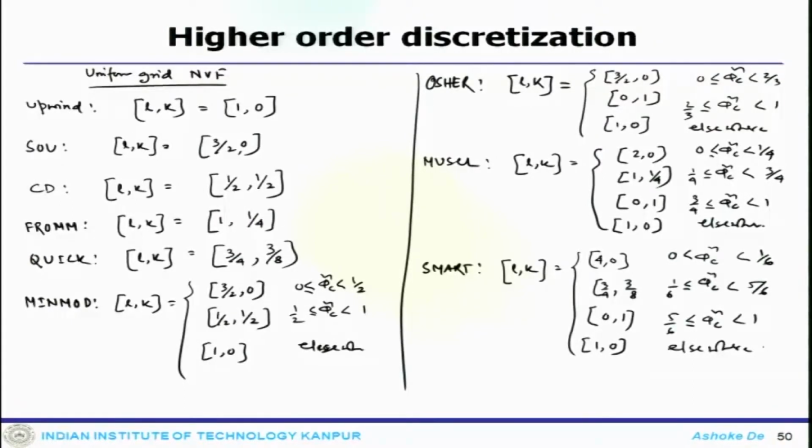Now, for an unstructured grid, this upstream node U is virtual. So, the term involving phi U is treated in deferred correction fashion, but the resulting source term, which will be in the form of 1 minus L minus K times phi U, is smaller than what would be obtained with the standard deferred correction.